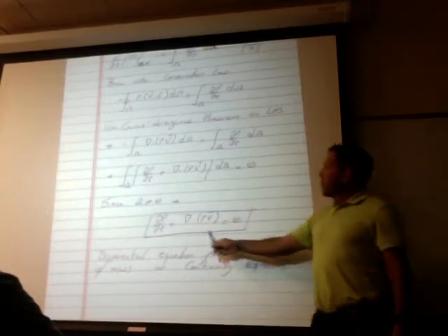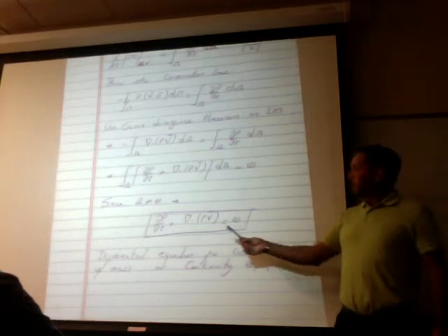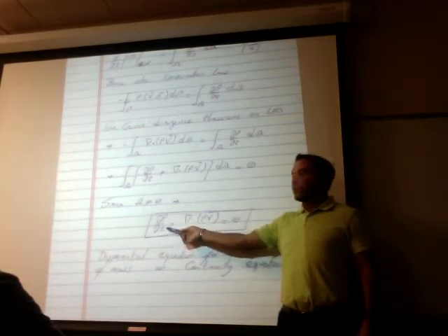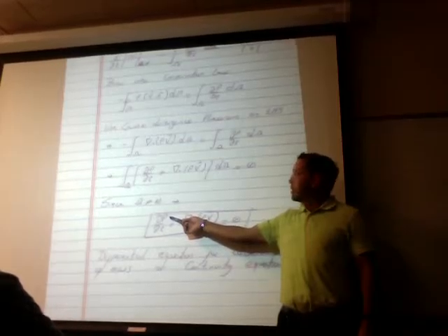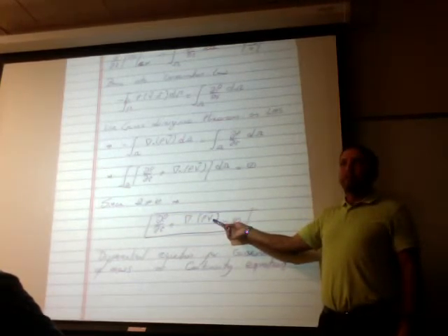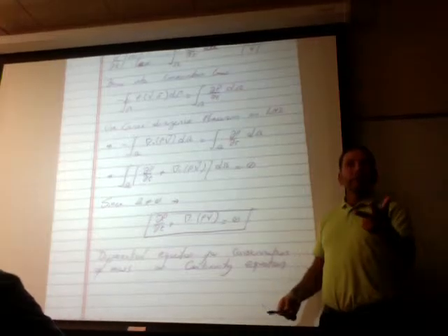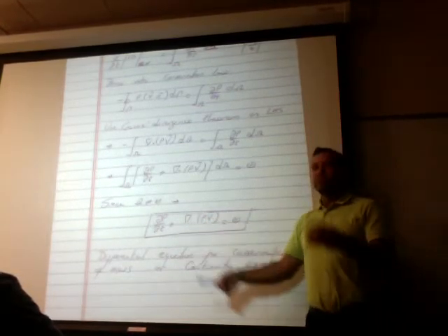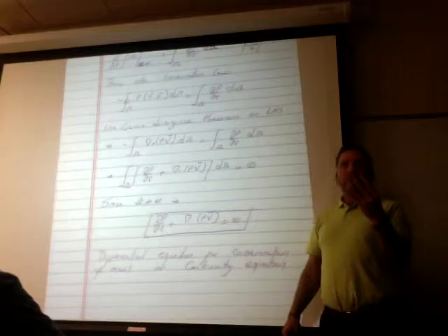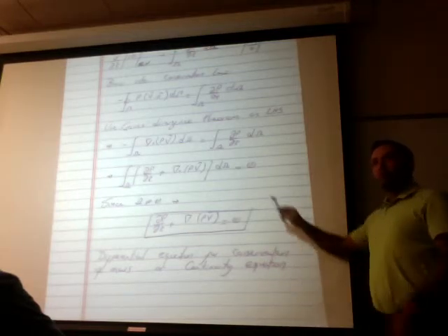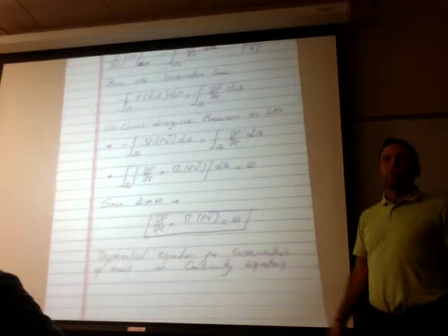All right. Now, can we solve that equation? The next part of this class, the second portion after exam number 1, we'll start by looking at differential equations and trying to solve them. Now, this is an equation that has how many unknowns? The density is an unknown. It's differential of density, so it's implicitly a function, right? And the velocity is 3 independent unknowns. Remember, the velocity has a u, v, and w component in general. So this is an equation for 4 unknowns. That's not solvable. It's underdetermined. So we need 3 other equations to complement the system, and that's what we call the Navier-Stokes equation.